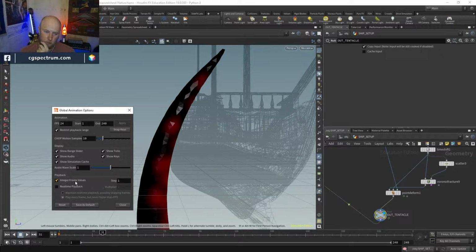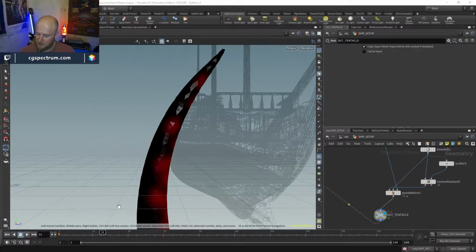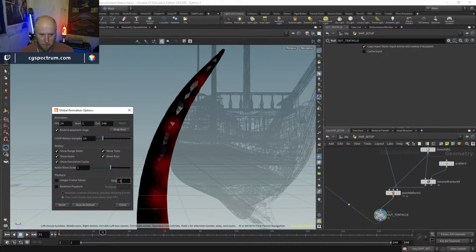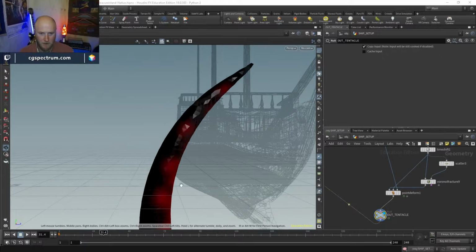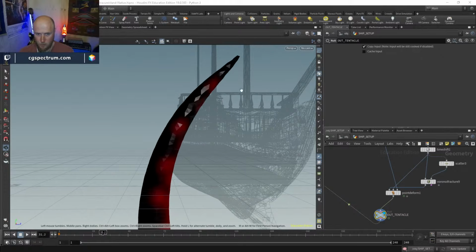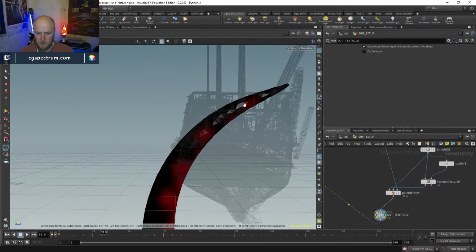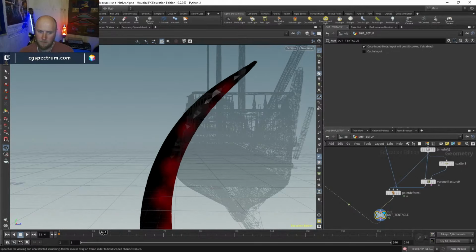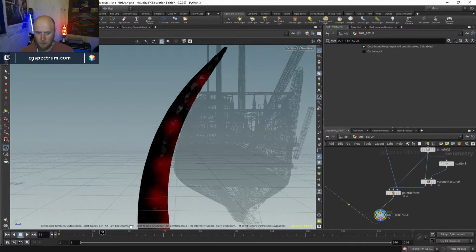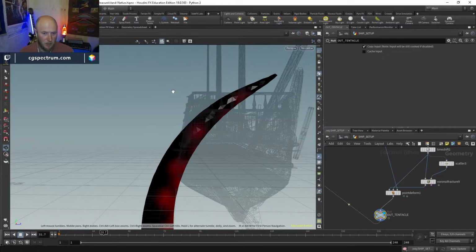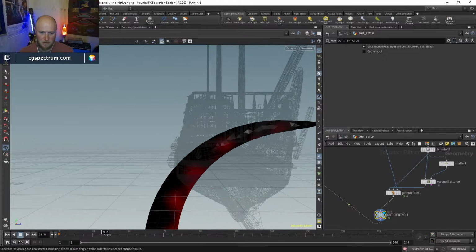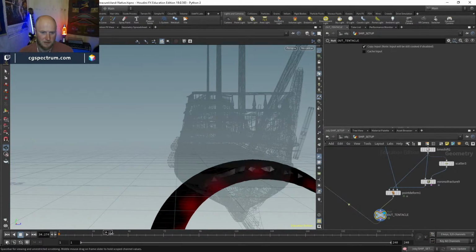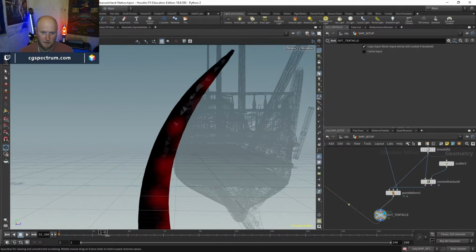Well, what I'm doing here is I need to make sure that if I turn off integer frame values and step through, actually I need to make my step 0.1. I just want to check that it's doing that. If it wasn't interpolating properly in the subframes, it would not be moving when I'm on 31.1, 31.2. It would jump every integer. Whenever I hit every integer, it wouldn't be doing this nice smooth interpolation. So that's good. That's what we want to see.